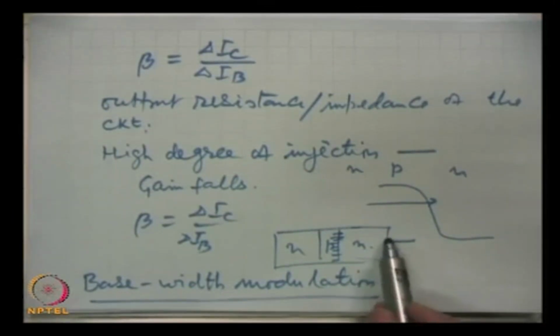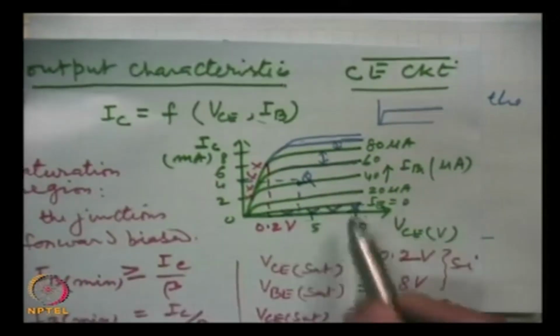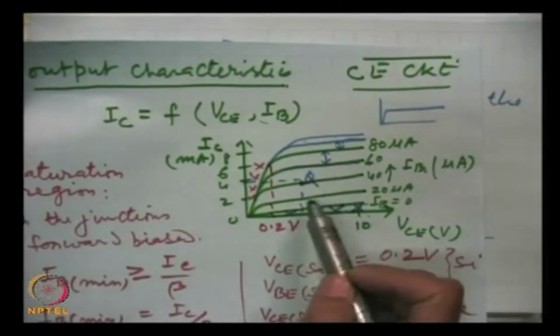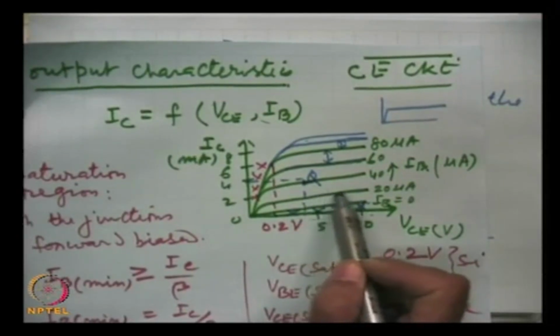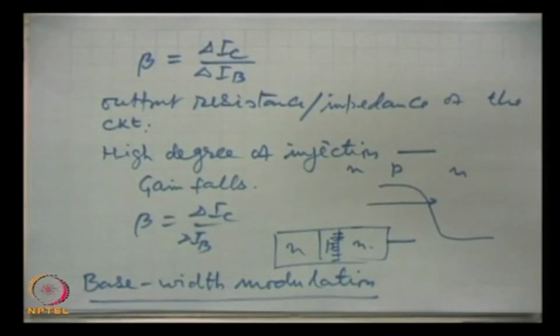With the rise of the reverse bias, the depletion width rises into the base, so a lesser number of charge carriers will recombine and the current will slightly rise. So, that explains these characteristics. We can get the current gain and the output impedance from the slope itself, and these are very useful characteristics. So, that covers the input and output characteristics of the transistor.